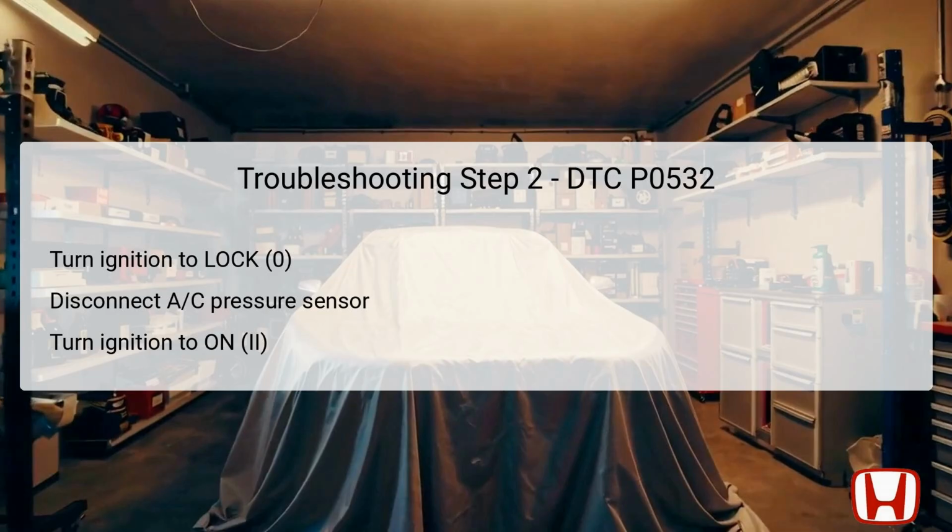At this stage, once again check the AC pressure sensor through the HDS. The same test will reveal if the voltage remains around 0.24 volts or less. A yes answer indicates you can advance to step 5 to potentially replace the AC pressure sensor. Otherwise, you should go to step 3 for further diagnostics.